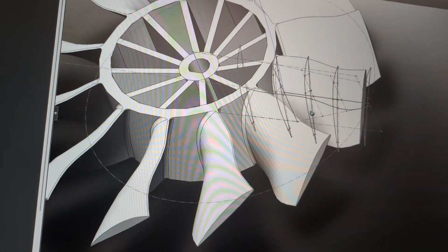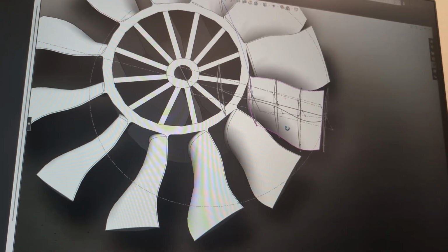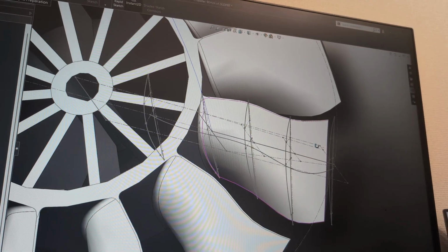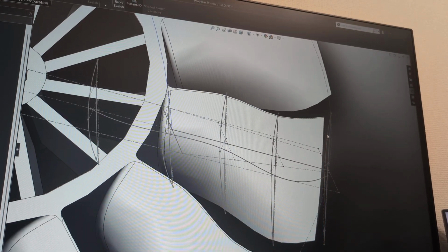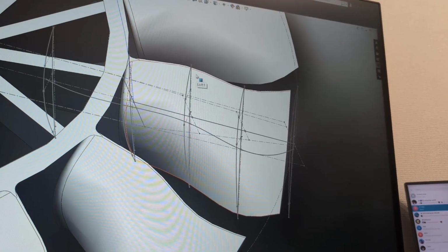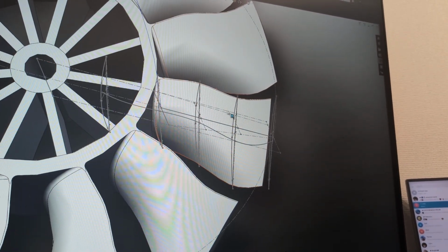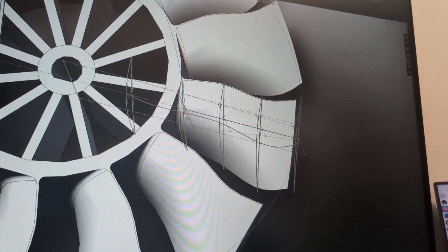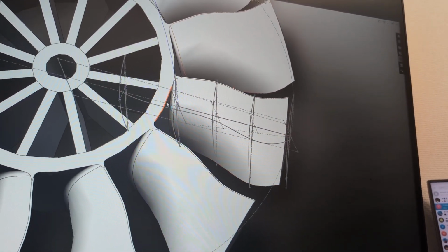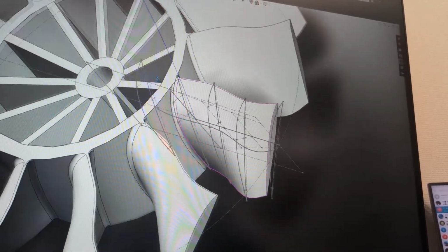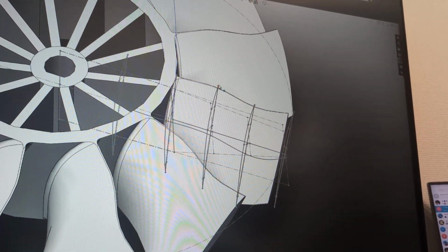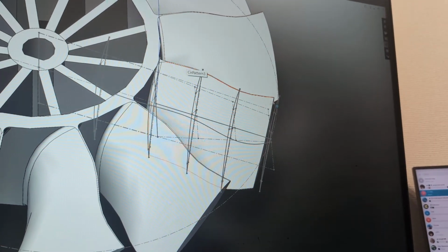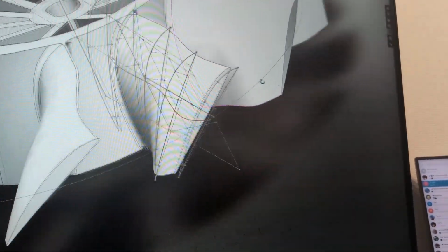Okay, so in order to make a nice and beautiful blade, you need at least 2, maybe 3 airfoil cuts, cross sections. I have 1, 2, 3, 5. One in here is just duplicating the root one. It's for design purposes. Unfortunately, I had to make it because otherwise it gives me a slightly wrong curvature.